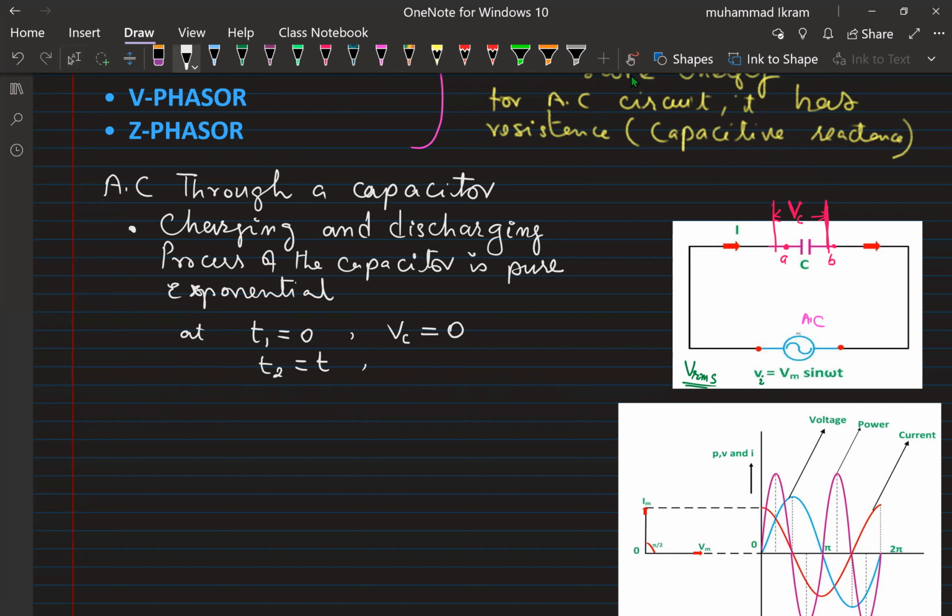Now when the potential difference builds up, for an ideal pure capacitive circuit, there will be a time reached for which the Vc across the capacitor may be equal to the instantaneous V. At that time, when Vc becomes Vmax, for example, the current in the circuit will fall to 0. Right in the beginning, the current I was Imax.